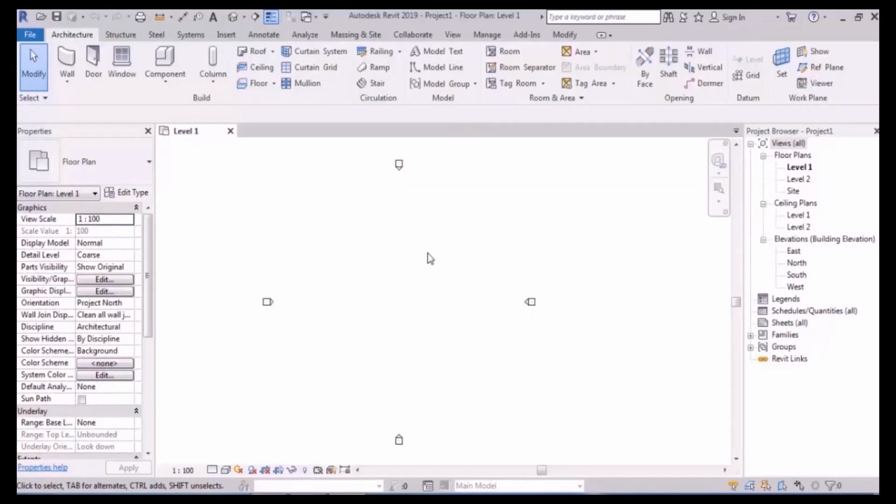Alright, now we are in the software and we want to analyze all of this in Revit. Well, to activate the stair, first of all we go to the Architecture tab and then Circulation, and then we can see the stair. In the old versions we had an arrow by the stair that when you opened it, it had 2 types. One of them was sketch, that fortunately it has been deleted because it was never useful. So I click on stair.